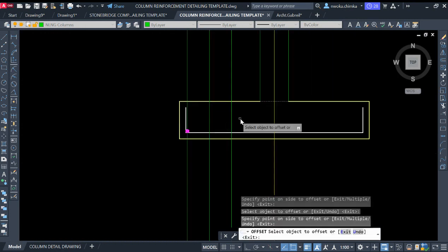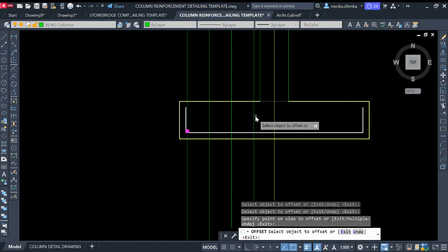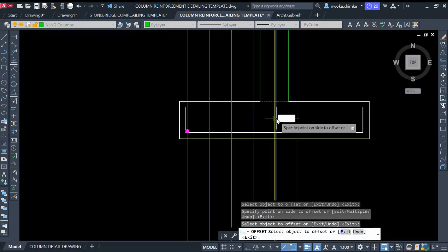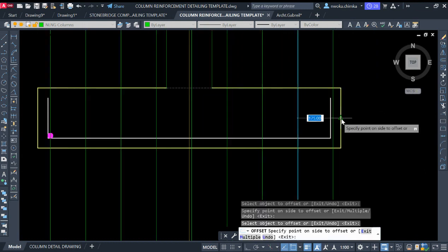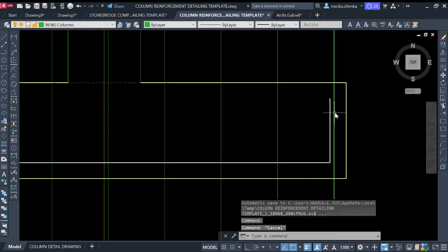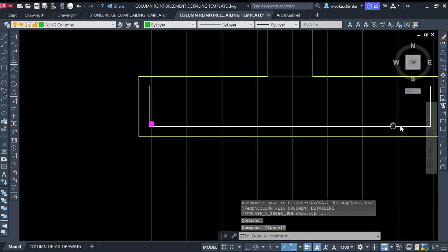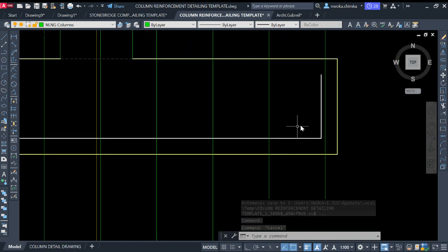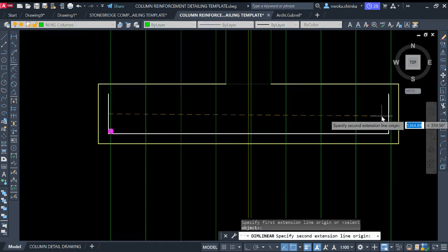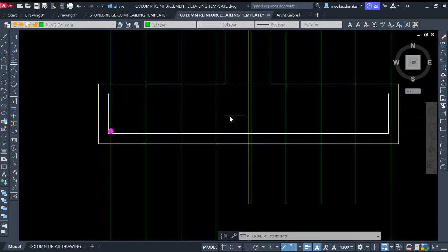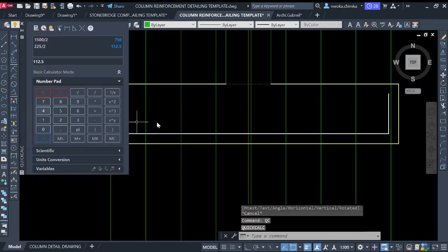You can see that click on this again, and again, and again, and then the last one will just fall in here. If it didn't fall in, because we used to have some kind of spacing, if you divide this now by 175, this right now, 1400 divided by the spacing 175, you see that you're going to have a decimal value.